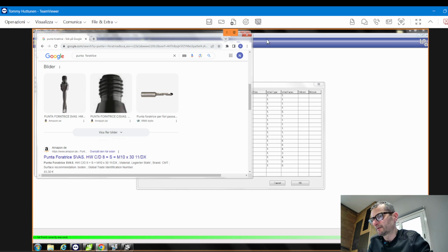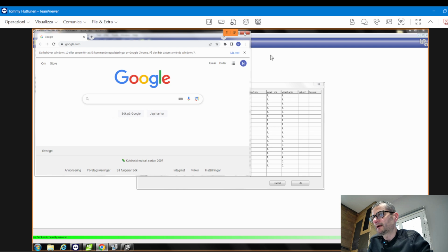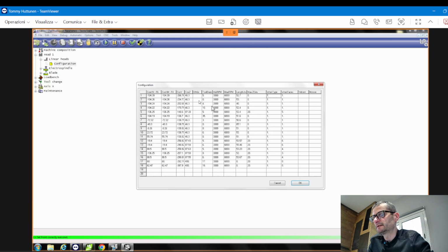There are several ways to fix this problem. One system is to create several different diameters here, for example 8 and 8.1. When I use 8, it's one kind of tool. When I use 8.1, it's a special tool, still 8mm, but to make the completely through bore in the panel, for example. Or you can use the work type.